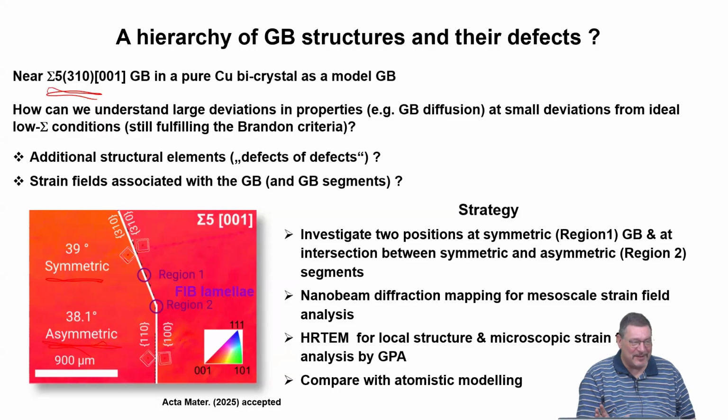This is an art in itself, to grow bicrystals, and not for all materials can you do it. The person who did this is specialized in growing bicrystals in copper, so we got this and we were very happy, because not everybody can do it. You need at least 10 years of experience to get a good bicrystal going, because all the small conditions are important to get a really good boundary. And even then, you don't get a perfect boundary. This is the best a person can do.